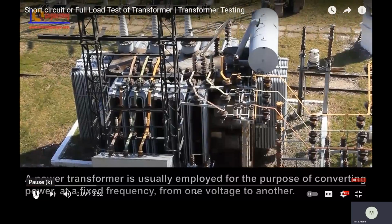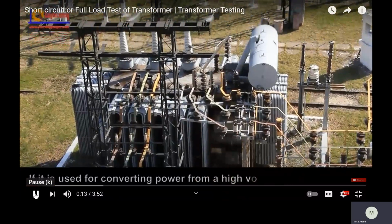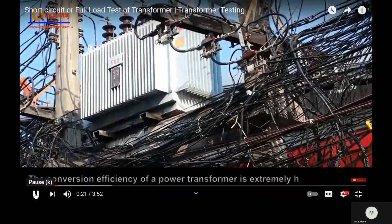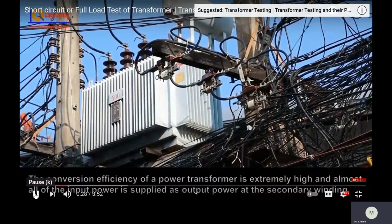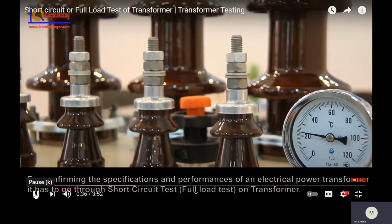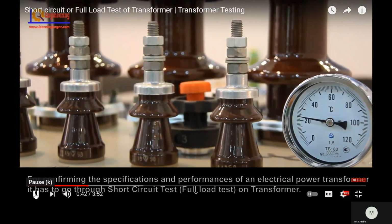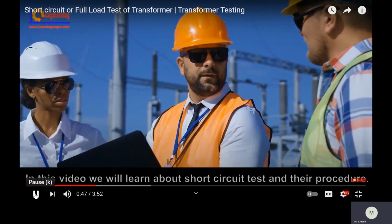If it is used for converting power from a high voltage to a low voltage, it is called a step-down transformer. The conversion efficiency of a power transformer is extremely high, and almost all of the input power is supplied as output power at the secondary winding. For confirming the specifications and performance of an electrical power transformer, it has to go through the short circuit test and full load test. In this video, we'll learn about the short circuit test and its procedure.